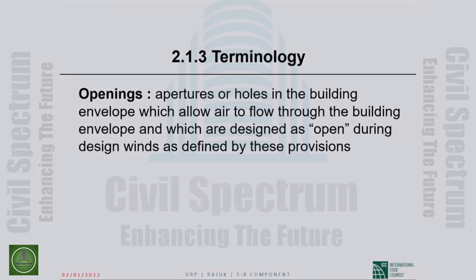So this becomes very important. You take a hangar or an automobile repair shop, those roll down doors, those are huge openings. If they're treated as openings, it can change the enclosure classification of the building. Are they openings? Are they enclosures? So you have to treat them as openings unless there is a crew in place and instructions in place to make sure that a roll down door will in fact be closed at the approach of a storm. Okay, otherwise they're openings.